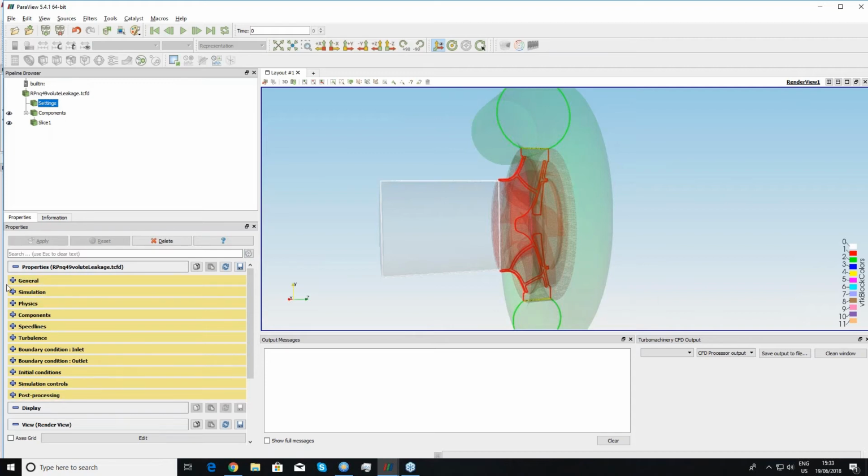This is really the most important and some of them compulsory parameters to be filled before you can run the CFD simulation. But anyway, using the CFturbo export, you will get these values preset. So there is no need to change almost anything. Just if you want to simulate a wider range of flow rates, you need to set it here. So let's go for that.